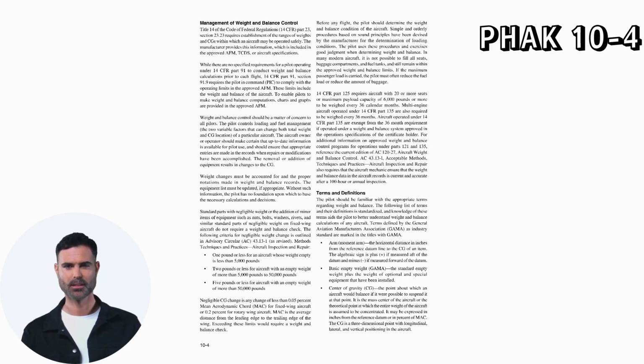Standard parts with negligible weight, or the addition of minor items of equipment such as nuts, bolts, washers, rivets, and similar standard parts of negligible weight on fixed-wing aircraft do not require a weight and balance check. The following criteria for negligible weight change is outlined in Advisory Circular AC 43.13-1 as revised, Methods, Techniques, and Practices, Aircraft Inspection and Repair.